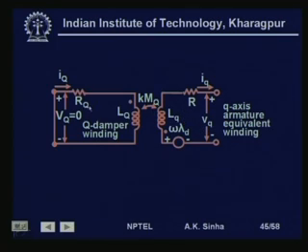Now, when the fault occurs, initial current will flow in the damper winding as well as in this quadrature axis winding, which are coupled, and since R will be much larger than L, this current decays very fast. So, initially we see the subtransient condition, and after this current decays out we get only the XQ part. So, we have in quadrature axis the subtransient reactance and then the quadrature axis reactance.